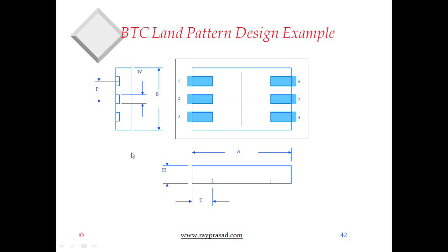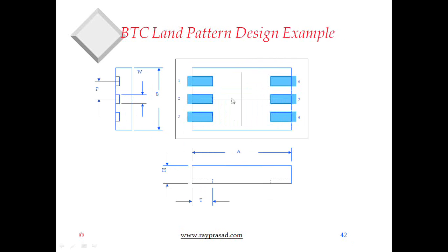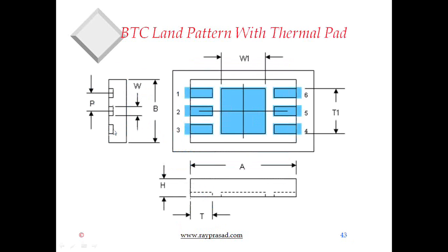Now on slide 42, we are just basically showing that you have to obviously maintain the pitch that's on the pad, the same pitch that you have on the component, obviously. You are trying to provide pad extension. This is explaining in a different way. And inner pad extension is not necessary. So slide 42 is showing you that there is no thermal pad in the middle. Slide 43 is showing that there is a thermal pad.